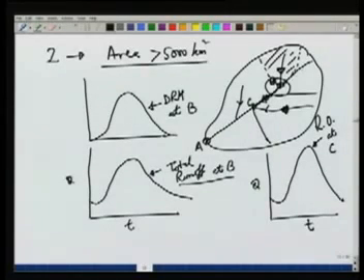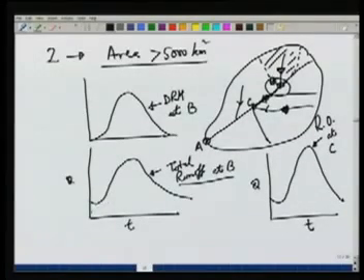Now the problem is that there is a time lag. So the time at which runoff occurs at point B and the time at which runoff occurs at point C, these time origins are not the same for these two graphs. Therefore, we have to do what is known as routing. In this case, we will have to route the flow through the channel, therefore it is called channel routing. In some cases, when we route the flow through a reservoir, we call it reservoir or storage routing. For example, in the Nash model, we have done some kind of storage or reservoir routing.